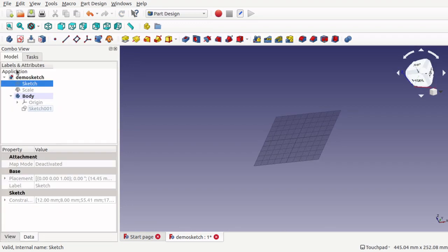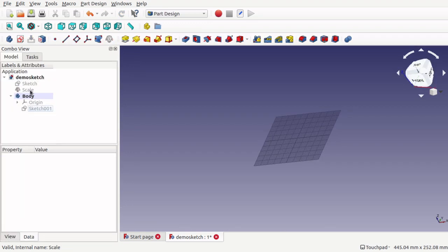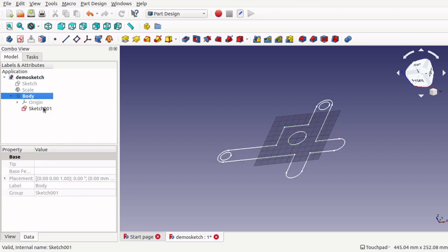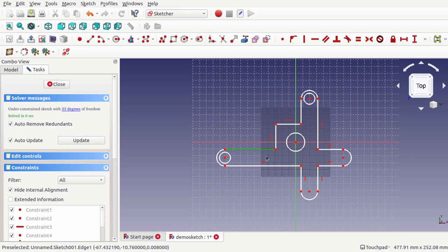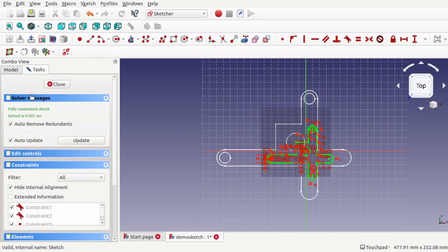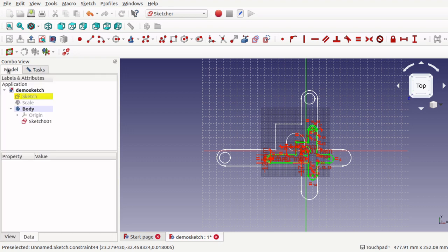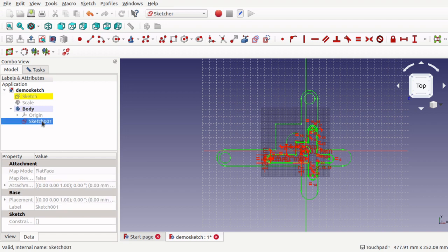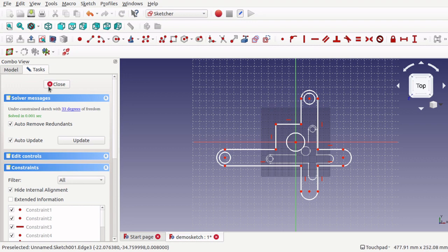That doesn't come through on the actual clone, because if we look at the sketch that's been created, so this one here, double click it, you can see none of this is actually constrained, so we would have to put all our constraints on there, where our original one has got all the constraints on there. So you would have to place all the constraints back on. It's just made basically a dumb clone of that sketch, but it hasn't pulled through all the constraints.